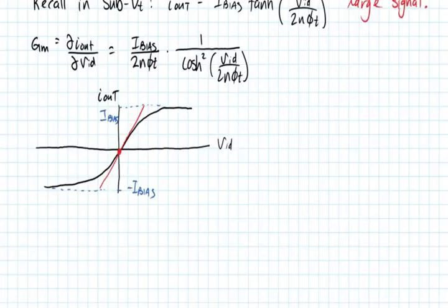Well, if we were to extrapolate this linear component of the circuit, you can only go as far as the rails. Now, of course, you're not going to get exactly that because there is some compressive nature to this circuit, but to a first order approximation, you could say that a box that would surround this extrapolated small signal model would be the linear range of the amplifier. Okay, and so what this implies is that the linear range is going to be fairly small, depending on what the slope of this line is.